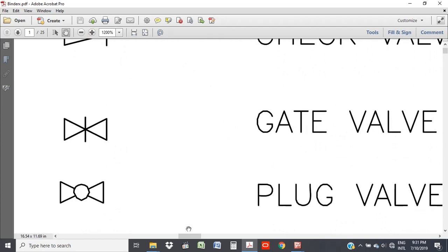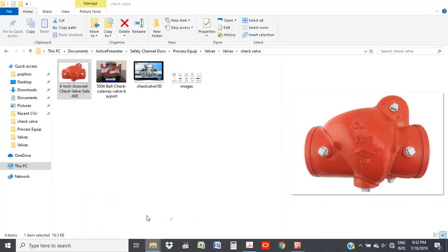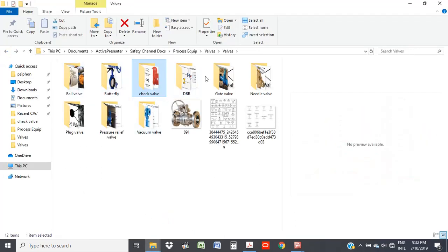And let me give a definition for it. A gate valve, generally, is the most common type of valve that's used in a process plant. It's a linear motion valve used to start or stop fluid flow. These valves are either in fully open or fully closed position. When the gate valve is fully opened, the disc of a gate valve is completely removed from the flow. You can't open it partially or slightly to restrict or control the flow. It has to be either totally open or totally closed.